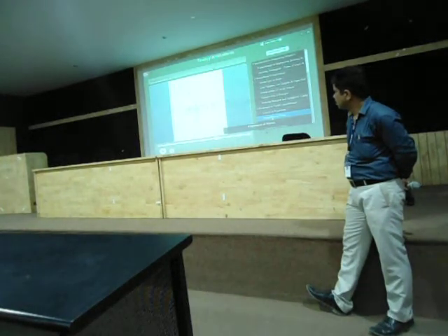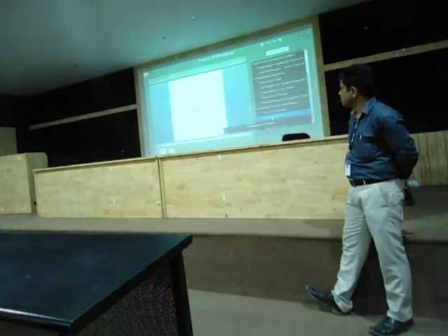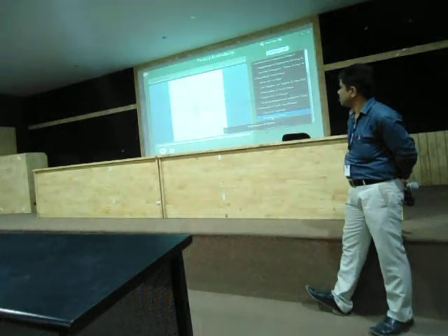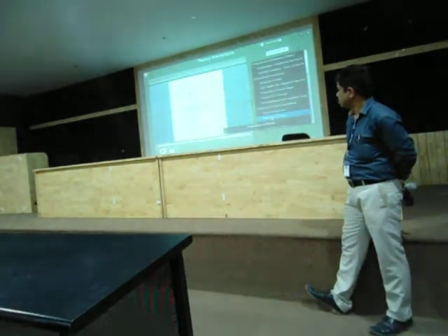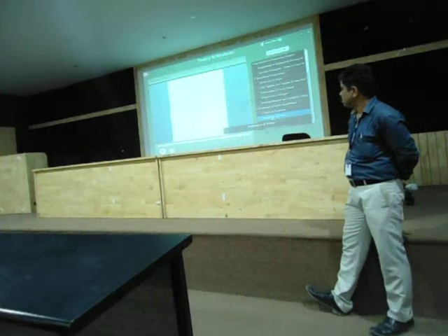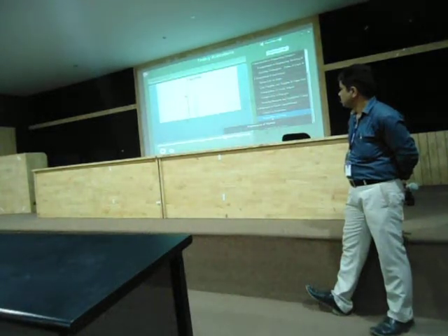The points A and A dash represent the images of the object on HP and VP respectively. The line joining A and A dash is the projector line and is perpendicular to the reference line XY. Observe, its front view will be lying below XY and its top view will be above XY.